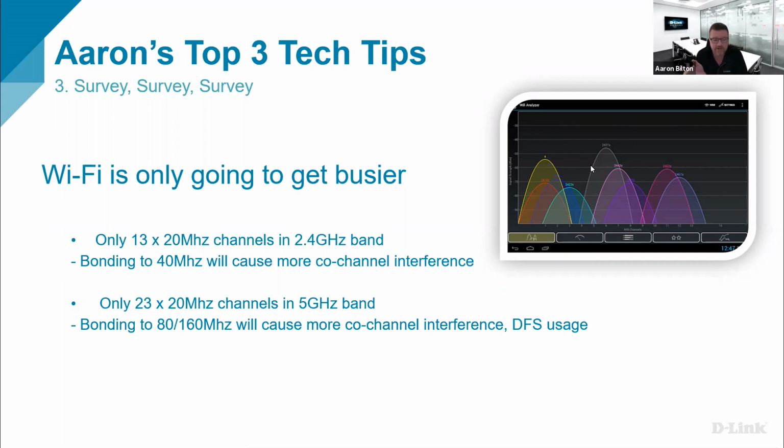But also in today's environment, we're getting very, very congested. Our frequencies are getting absolutely hammered, and it's only going to get worse. We've got Wi-Fi AX coming, well, it's here, sorry, which can use both bands at the same time. And depending on power levels and channel widths, you can blow away both bands on one AP.